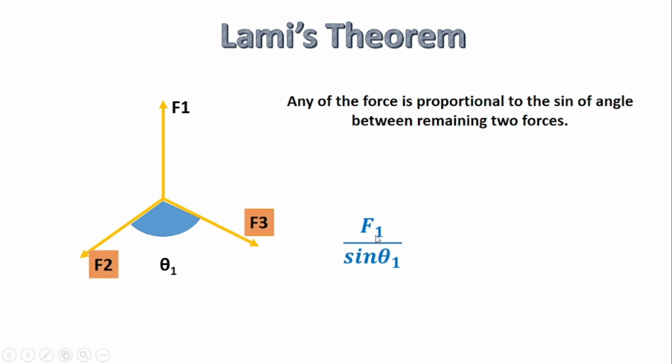But here I will directly write the equation of Lami's theorem because the derivation is not that important. It is not going to be asked in the final exam. But the application of Lami's theorem is always there for the concurrent force system. So we'll understand what the final equation of Lami's theorem is. F1 divided by sine theta 1.